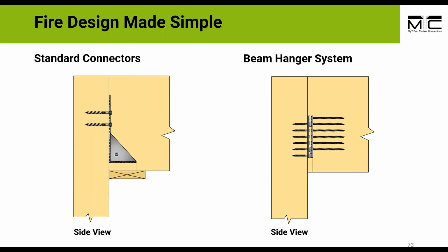For the standard connector, you need to calculate to see if you actually need additional wood covers at the bottom. For this one, you needed more. You have to make sure that it's tightly screwed in and the screws have enough length to keep that protection in place. We did the calculations again and we needed another piece, and you have to screw that piece again.